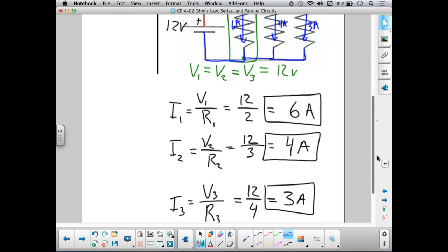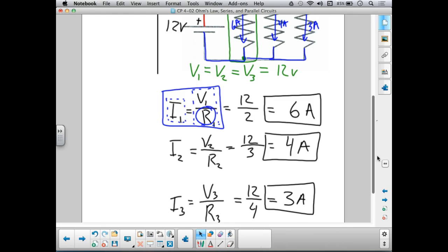Another way of thinking about it is to zoom in on just the Ohm's law equation, I equals V over R. Because R is on the bottom of this fraction, in the denominator, making R bigger makes this whole fraction smaller, which means that if I is equal to that fraction, I is going to get smaller as well. So we see mathematically that works out too. The bigger the resistance, the smaller the current.